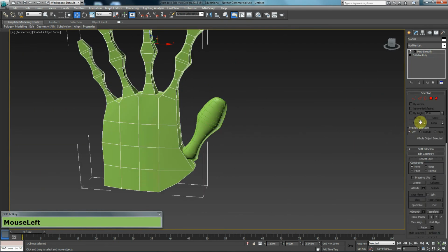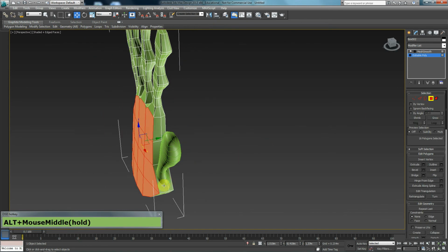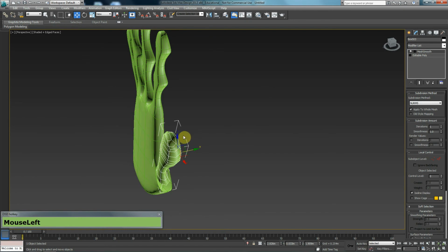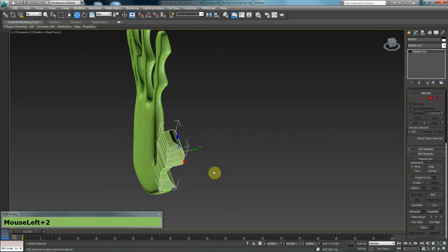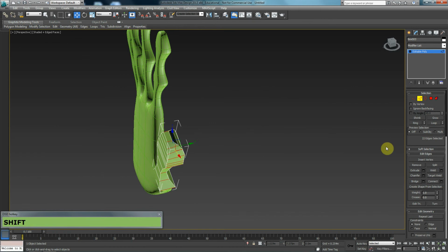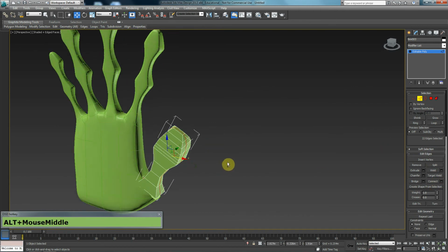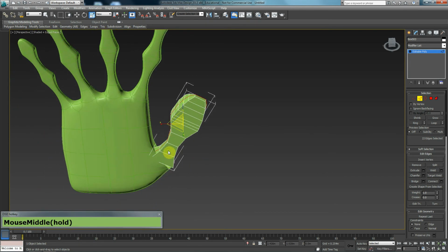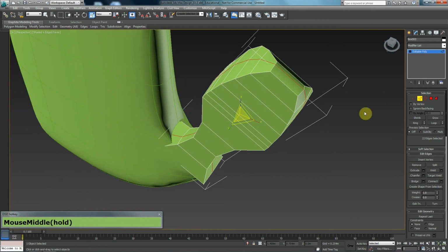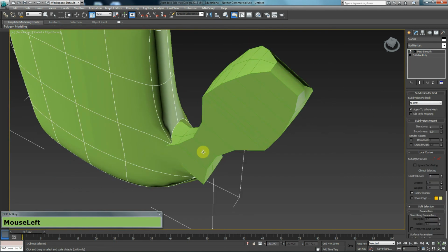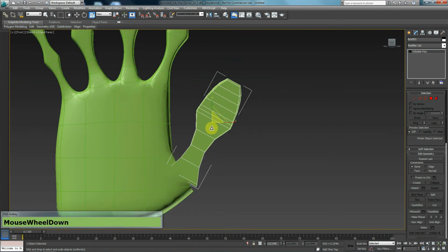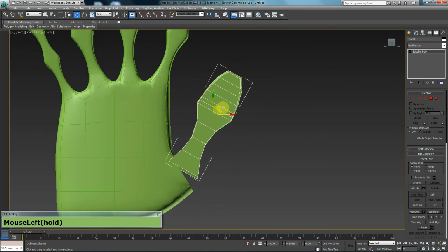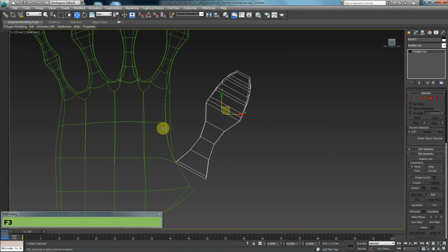and editable poly, delete that. What I actually want to do is, I don't want two mesh smooths, so I want to delete the mesh smooth on this. Also, I may want to make one connection there, not three, just one, and maybe expand that a little bit. And I'm adding this additional line there because I have it on my base mesh.